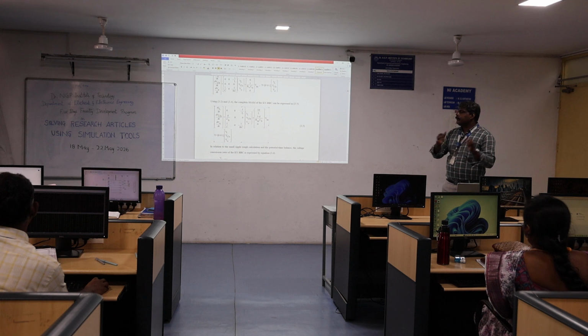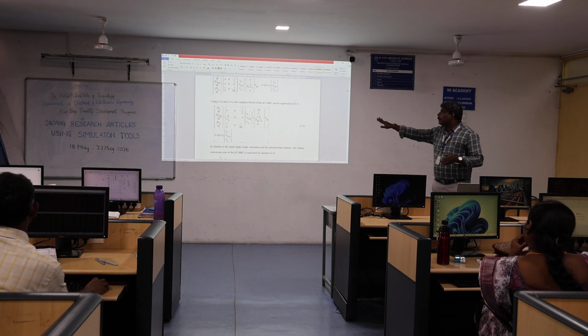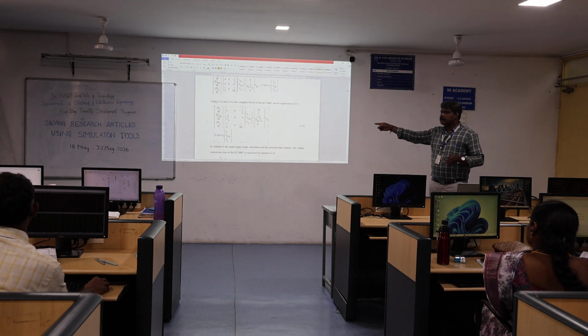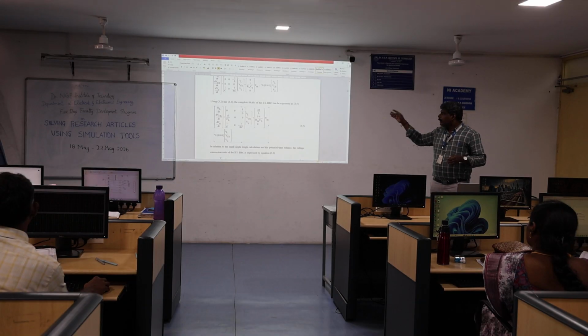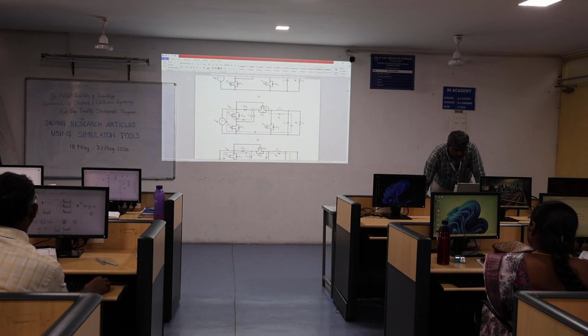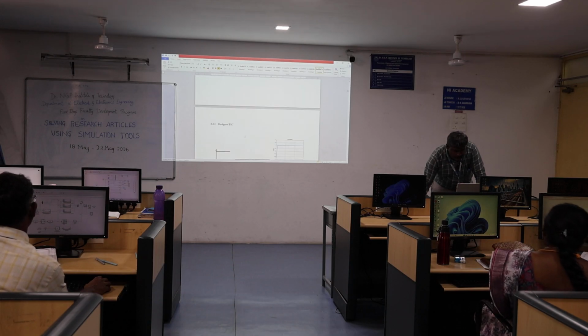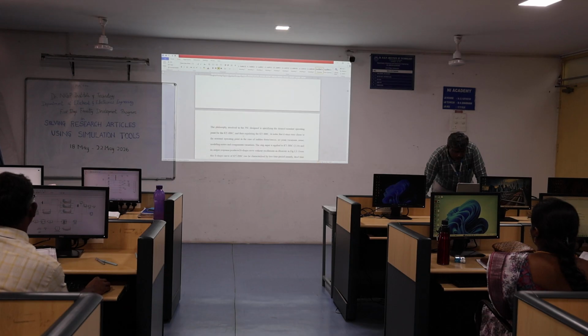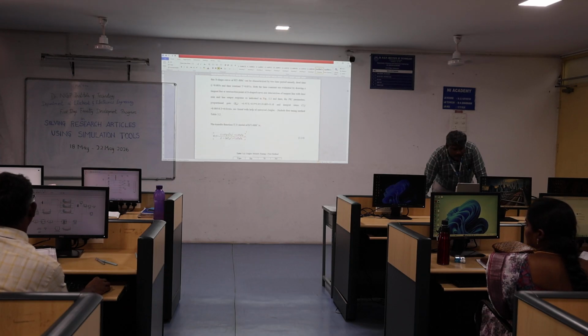That numerical data you just type in; this is called the A matrix. Similarly for the B matrix. Similarly next the C matrix. Then D matrix 0. Then if you type it, you will get the transfer function. So this is the way we are going to obtain the transfer function. So to this transfer function we are going to apply the step response.